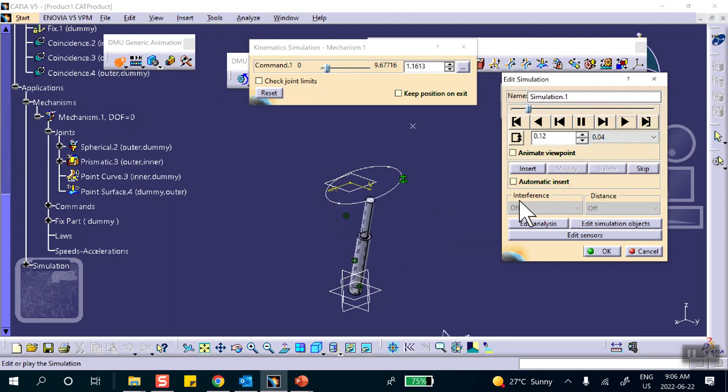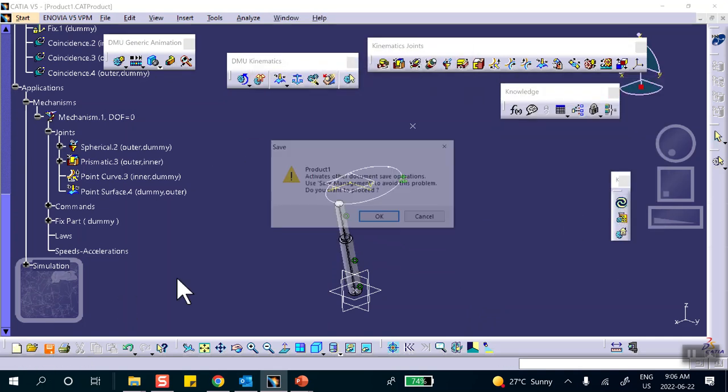So that's what the problem was. What you learn here is that 1 extra persisting degree of freedom, which is happening between spinning of 2 endpoints, possible spinning of, but because of the nature of the endpoints, which is in one case ball socket, the other one was point curve, or it could have been ball socket, ball socket. So ball socket means that that piece in between can always spin, and this is one way to get rid of it. Okay, there are other ways of doing it. So let me stop this thing, rewind, okay, save everything.